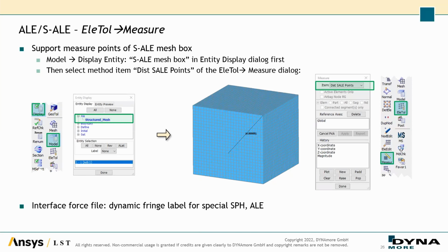Since LS-DYNA 9, the release contains a new structured ALE solver, dedicated to solving ALE problems which use structured mesh. And LS-PrePost supports measure points of the SALE mesh box. You have to go at first to the display entity interface and show the SALE mesh box, and then go to element tools measure and select the measure item dist SALE points to measure between or in the SALE mesh box.